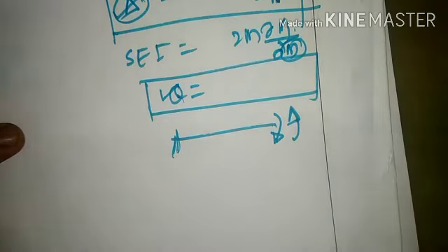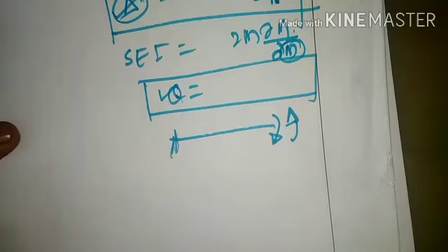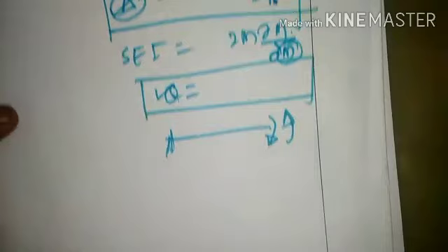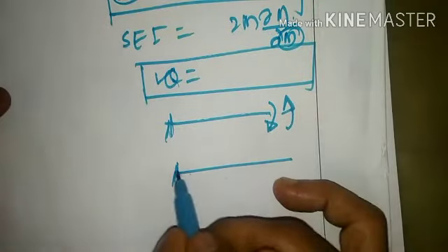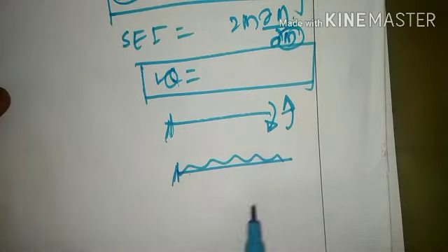For that reason, if we have a moment, well and good. If we don't, then we need to introduce a dummy or fictitious moment at the position where slope needs to be calculated, and then partially differentiate with respect to that moment. The same condition prevails if I have a cantilever beam carrying a UDL here.